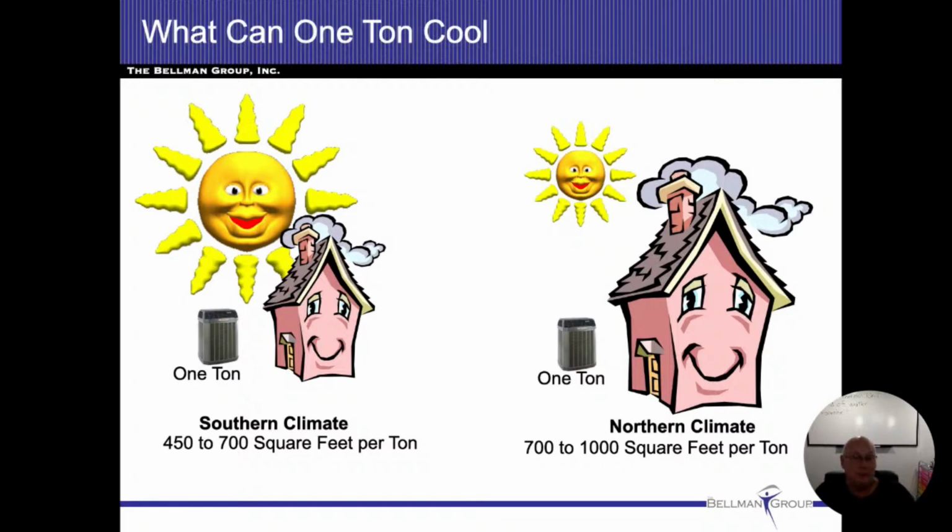All right. So a decent rule of thumb is about 1 ton for every 1,000 square feet. You really don't see too many systems smaller than 2 or 2.5 tons. Most of the ones we're going to run into, the smaller homes, are going to be about 2.5 tons. In my house, I do not have a big home. We have a 2-zone system, so they don't really run all that much. It's roughly about 1,500 square feet, and I have 2 separate zones, and they're both 2.5 tons.